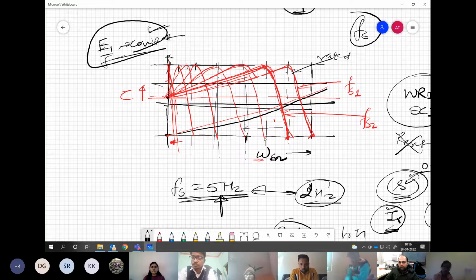So these are all different synchronous frequencies where the motor is operating. Slowly you can reach a point where the slip frequency may be a very small number, which is actually your operating frequency itself in terms of the actual physical rotational speed. Then slowly we can go on increasing the synchronous frequency, and we can come back to the actual operating point wherever we want. Actually, we can operate anywhere. There is no problem. The same motor can be operated with any frequency up to the rated frequency, even beyond that, but then certain things change.